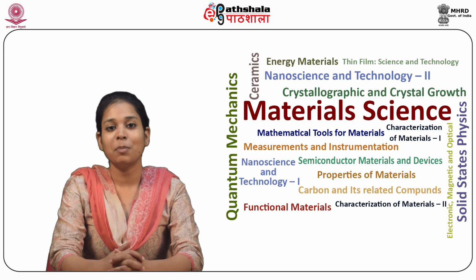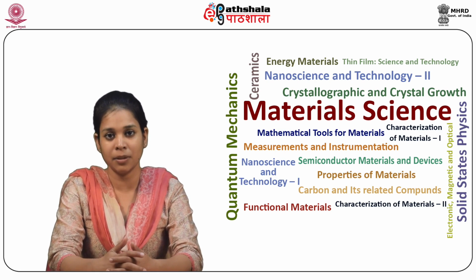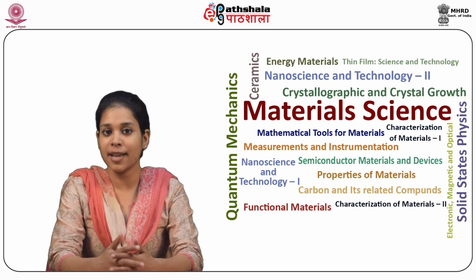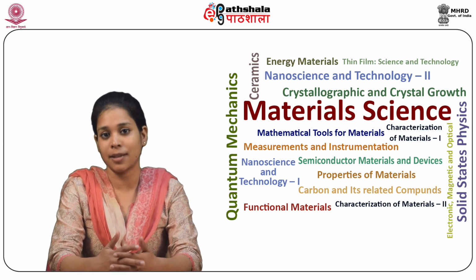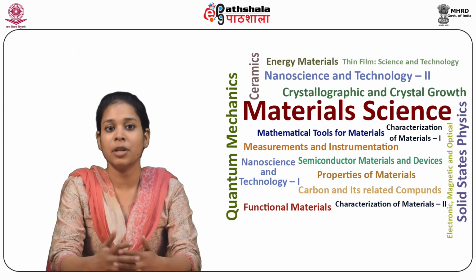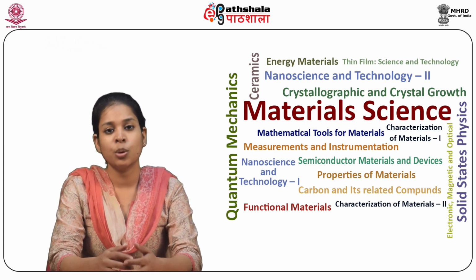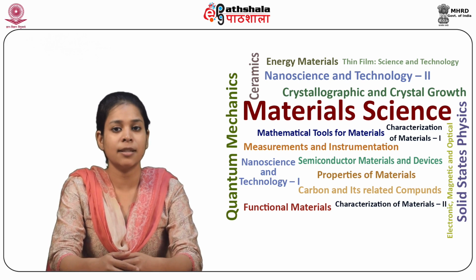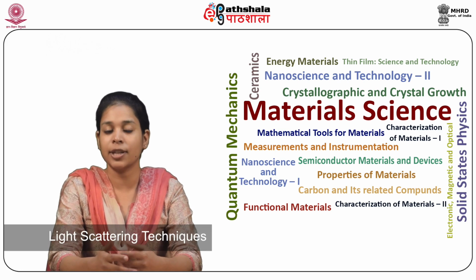So in particle size measurement, there are several techniques available. The choice of a technique depends on the expected range of particle size, the cost of the measuring instrument, the time available to perform the measurement, and so on. Sometimes two or more techniques may be required to cover the whole range of sizes in a sample. The common techniques used are sieving, microscopy, sedimentation of particles, and light scattering techniques.